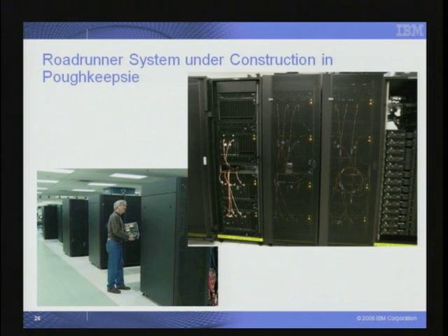Yes. A question or a comment about, said, more compute power per soft error. Not sure I agree with you there. Maybe yes, maybe no. True, the number of whole electron pairs per square millimeter of silicon will be constant, but the devices are getting smaller, they're getting closer together, and the number of your double bit and even triple bit errors is zooming up, depending upon your architecture and your error detection and correction circuitry.